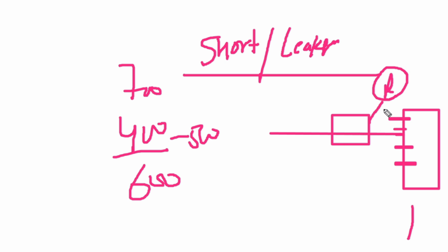So getting back to the topic, some people ask, why remove this resistance? Because most of the time in this circuit there is one cap. Also sometimes there is no component installed, only a resistance directly connected to the display connector after this line. Clear? So why remove this resistance?